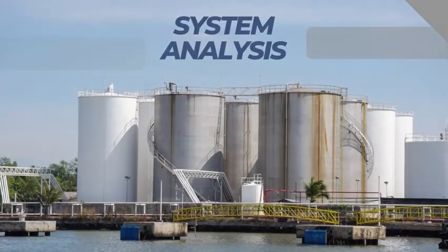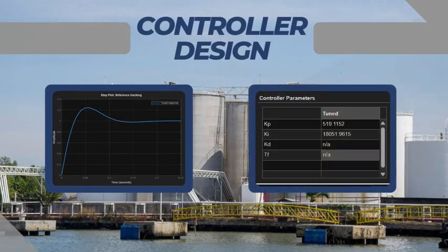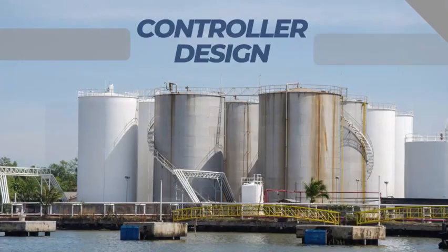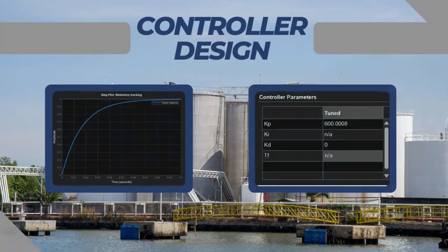2.4 Z-domain. Convert to Z-domain with Tustin. Use digital PID controller. Analyze with Bode plot and step response. 3. Controller design. Design all 3 types: PI, PD, PID controllers. Display Kp, Ki, Kd parameters. Use PID tuner and adjust bandwidth and phase margin values.